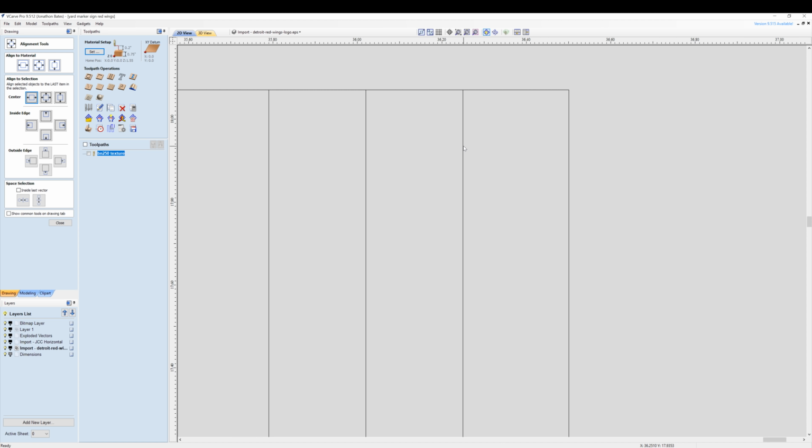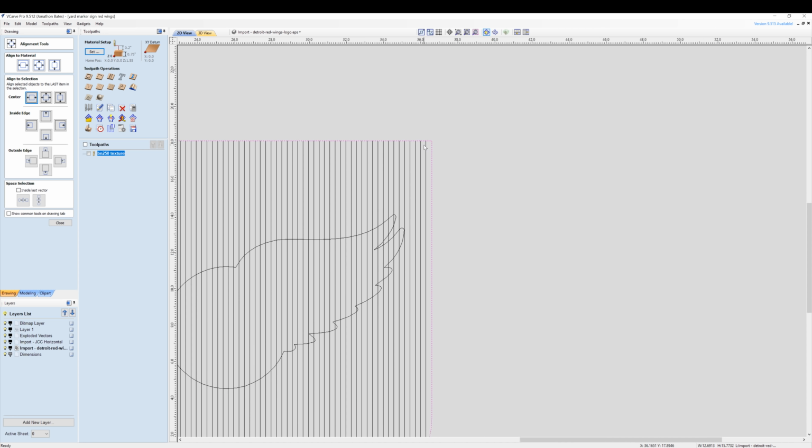And that means that as the bit travels along this path, I'm not going to accidentally mess up the perimeter at all. And it's not going to cut all the way. The bit's going to stop somewhere like right here. So I will have some uncut area to the right of it. But that's okay, because once all of the fluting is done, I'm going to make a perimeter cut on the inside of this line with that same bit to just clean up all of the ends.